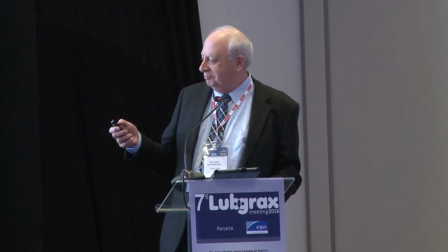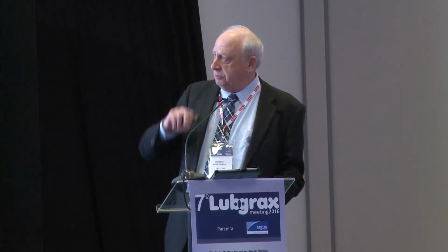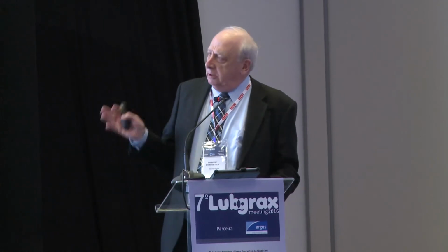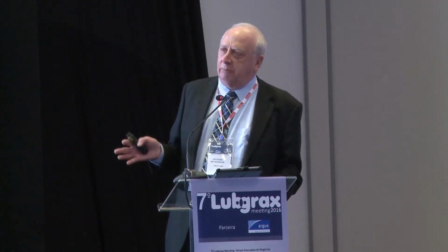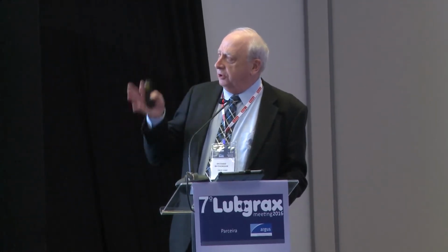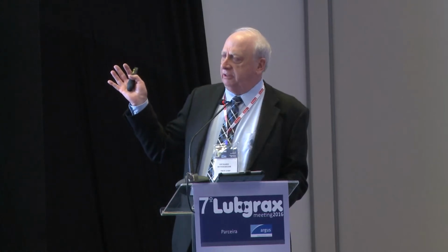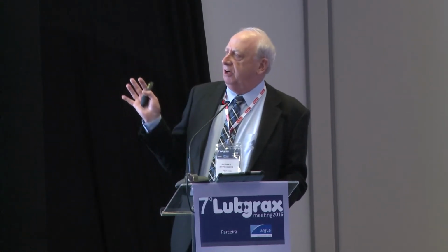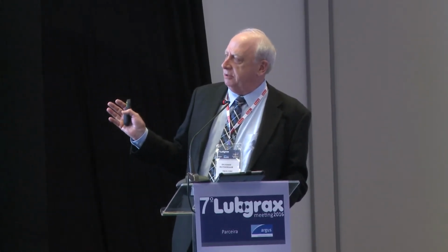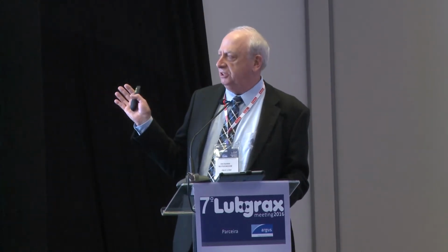The ideal. Some of the things you should be monitoring in terms of managing the system. The pH. If the pH is stable, it's a good indicator the system is under control. The fluid concentration, the odor, the appearance, bacterial counts and fungal counts. These are things you should be doing on a routine basis. Ideally, you want to know the bactericidal levels and the fungicidal levels.